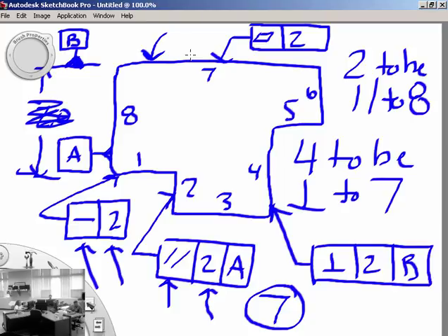The art of quality control, and it really is an art, is all about figuring out how to set up jigs and tools to check things like this. The go-to move is to use a CMM machine to check the measurements for you, but a lot of times templates and jigs can be used very effectively. It's a little beyond the scope of what we're talking about, but somebody's got to figure it out. You won't be able to gauge this with manual tricks.